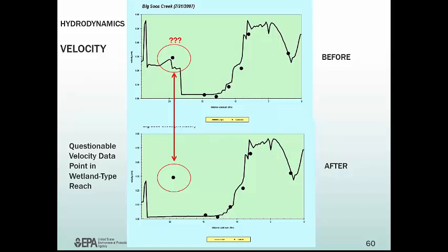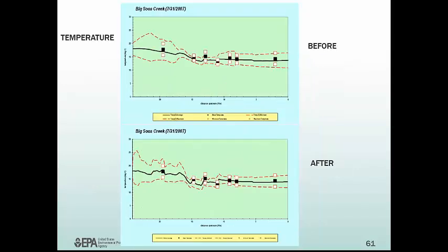After the physical properties, we move on to temperature, one of the more straightforward water quality parameters. Note that here, QUAL2Kw is a steady state model and gives a snapshot. However, what I didn't say was that it's actually quasi-steady state, meaning that it gives a snapshot of one day. So we run one day of variability into this model, and it gives you a min, a max, and a mean for that day. So that's why I have these hatched red lines. The solid black line is the mean estimate, and the hatched lines are the min and the max.